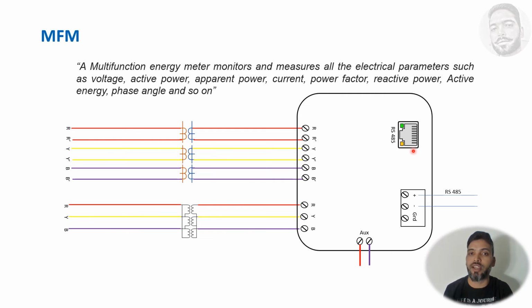For example, you have 30 devices. How will your RTU understand which device is which? So you have to address those devices also, like a slave address. The first device is from my incomer, so my first device is 1. Like this, 2, 3, 4, 5. You can put around 30 devices, maybe more than 30. As per my knowledge, around 40 devices in a chain, and you can communicate. Those devices will communicate with the RTU, and that's called the multi-drop method. I will show in my next video, next part, how it works.